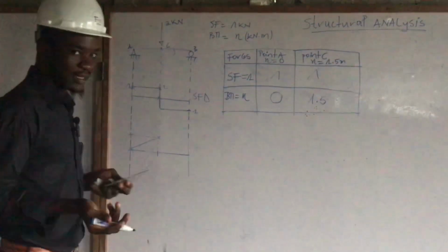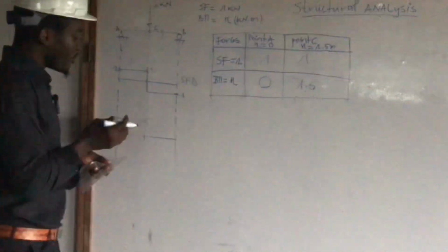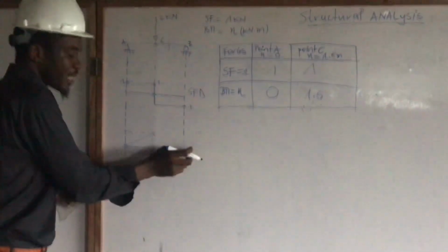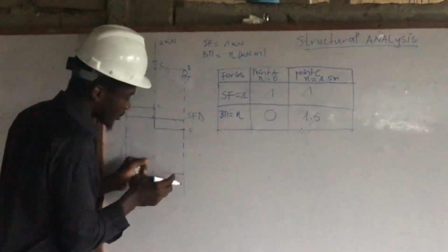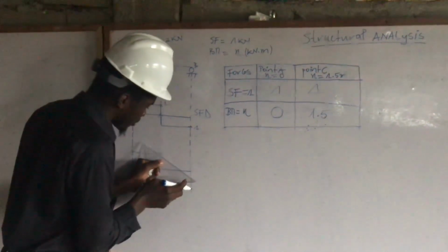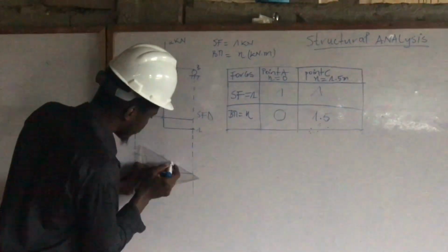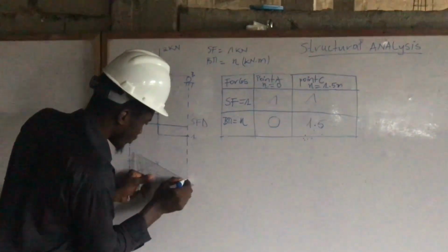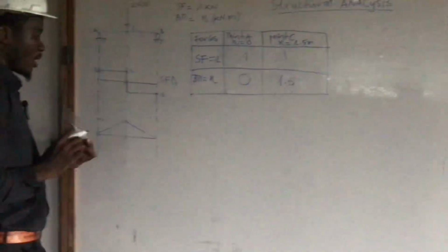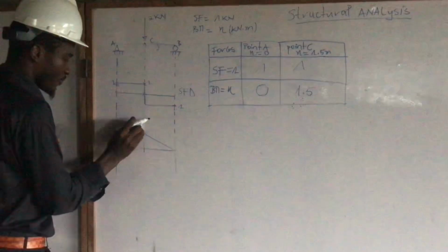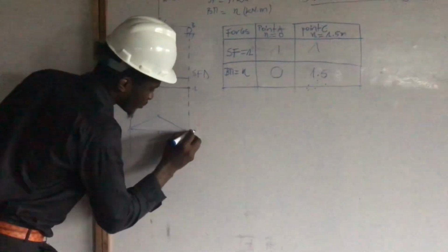Okay, and as I said, it's a simply supported beam with a concentrated load. So the behavior of the structure on this side will be the same here, but just of negative sign. That's the implication, and it's normal because at the end we can notice that we have a roller support on the other side. So let's just draw. So this will be our bending moment diagram. Let me remove the dotted line. Okay, so here we have 0.